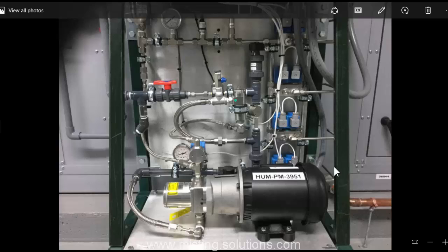Now there's actually a little better way to do it that I'll probably implement on future systems, but it requires another solenoid valve yet. I've already got 10 in here, so what's another one? But basically it would be a T coming off here where the high pressure was, another solenoid valve, and then take it over to the dump line, which is right over here. It would be a normally open valve, closed when the system is running, and then when the system shuts down, the zone 1 has finally shut off, that valve would open up and dump any of the high pressure water that's in this line, dump it to the dump line.